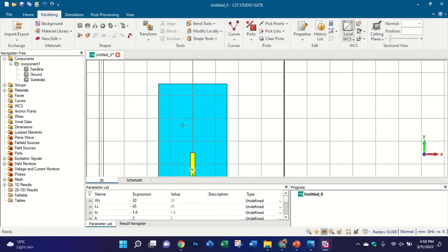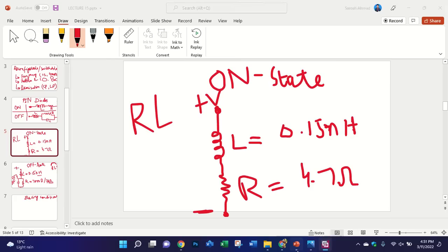I want to ask you something about using the PIN diode. You connect it to a metallic bar. The gap between it, does it have a fixed value? This gap, or can we do it as you want? Of course it will become small, but has no standard value. Yes, the gap should be 1 cross 1 millimeter square or less.